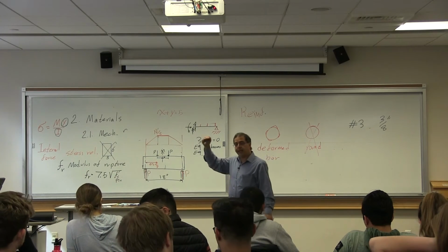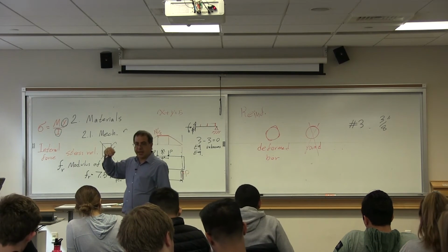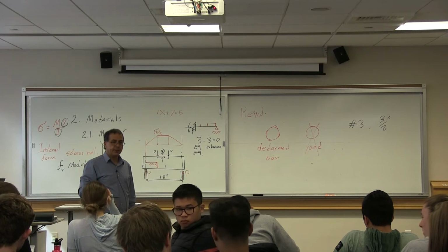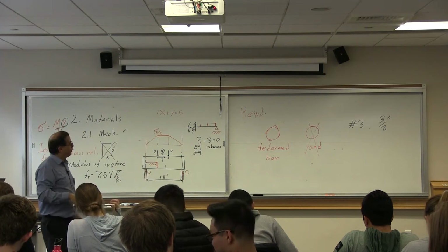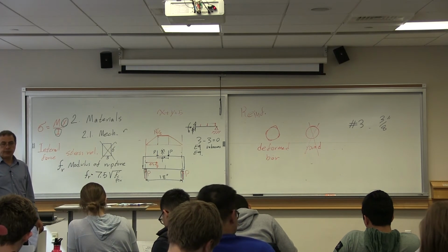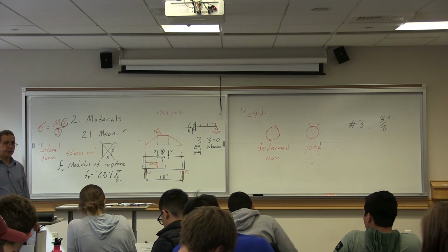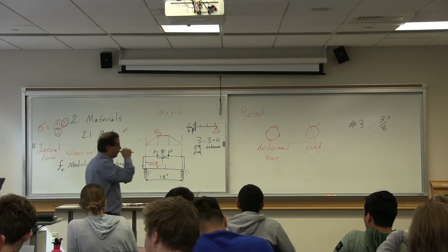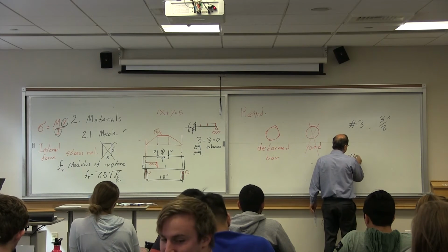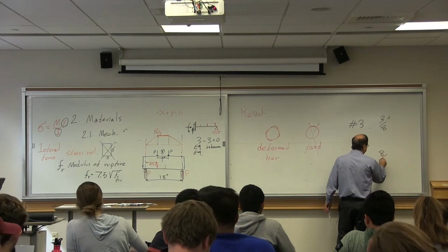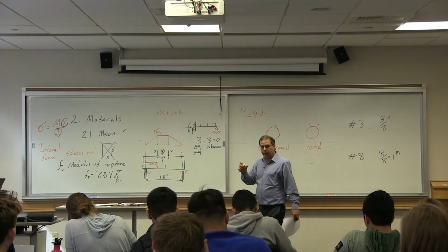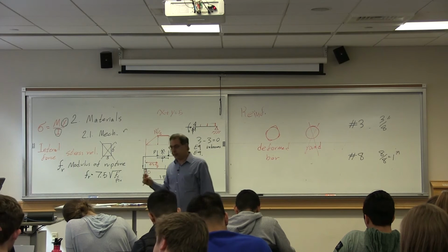Up to number 8, the diameter of the bar is the bar's number divided by 8. That means if I say what's the size of number 8, the diameter of number 8 is 8 divided by 8, which is 1 inch. So the diameter of number 8 bar is 1 inch.